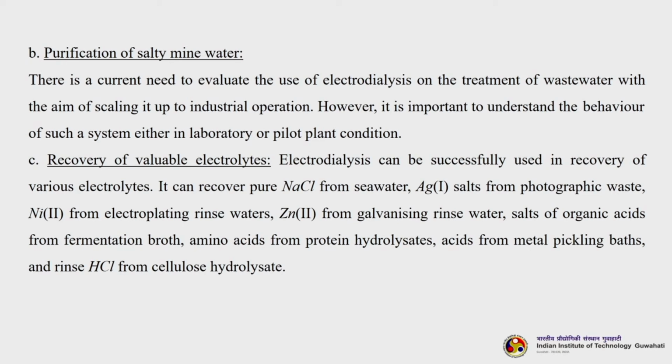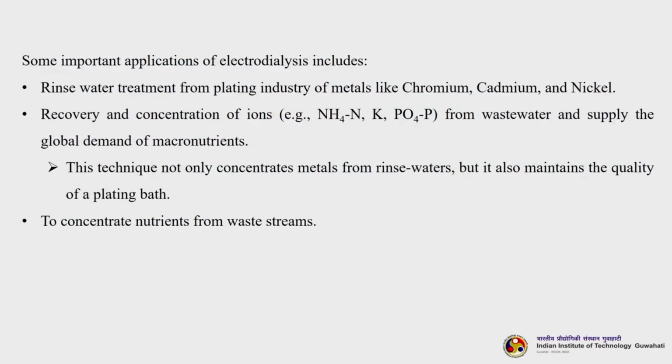It can recover pure sodium chloride from seawater, then silver salts from photographic waste, nickel from electroplating rinse waters, zinc from galvanizing rinse water, salts of organic acids from fermentation broth, amino acids from protein hydrolysates, acids from metal pickling baths, and hydrochloric acid from cellulose hydrolysate. So, you can see that there are so many applications of electrodialysis.